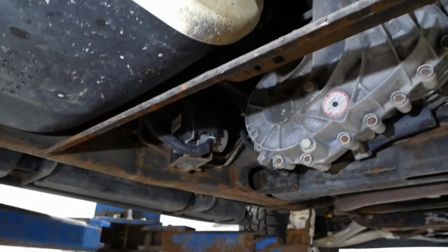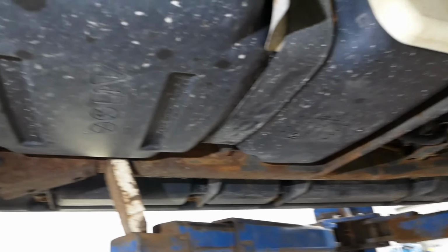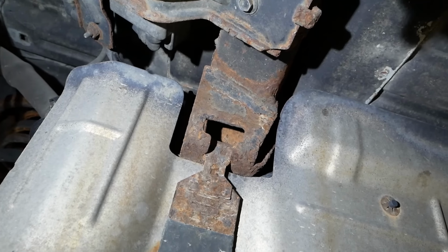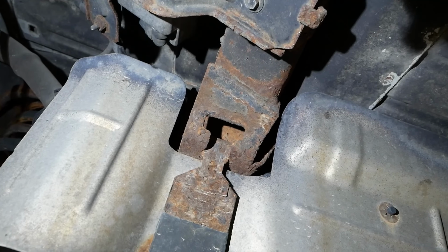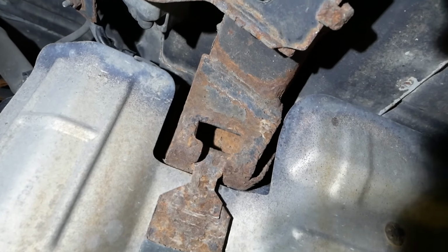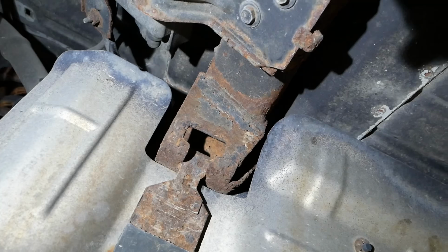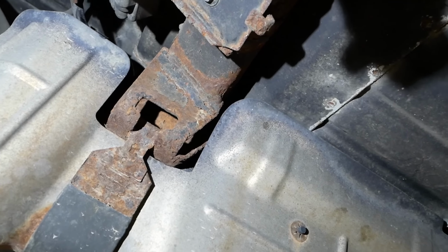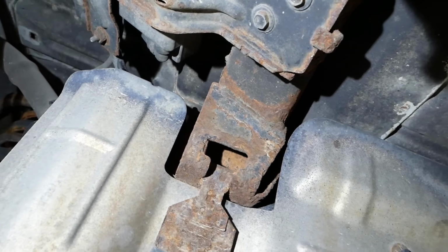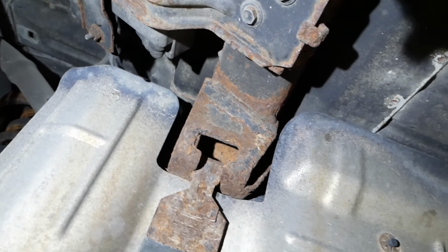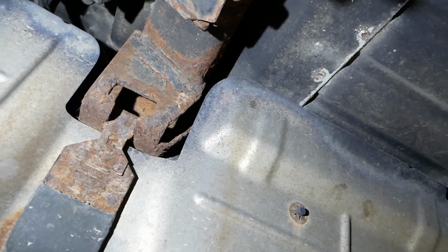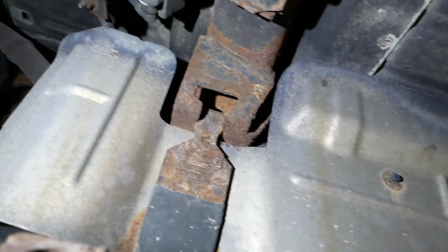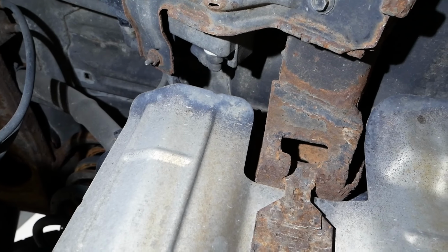It's not the purge valve. It's not the vent valve. I'm thinking, just based on experience with these older GMs, it's probably the fuel pump. It's a plastic tank, but usually it's a steel pump, or at least a steel lock ring, and they get all corroded and rotten on the top of the tank, and yeah, the lines break off, or it cracks the top of the pump. So I think we're gonna have to drop the tank in order to identify this problem.